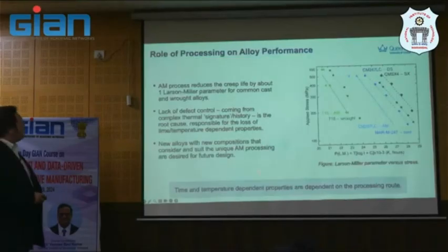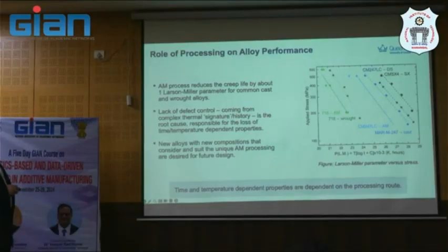We were inspired by the performance of alloys, where AM reduced the creep life by about 1 order of magnitude in the Larson-Miller parameter. It shows CM247, a single crystal superalloy. When you change to directional solidification, you get a lower creep life in the Larson-Miller plot. If you then do additive manufacturing in the same material, the creep life is reduced further.